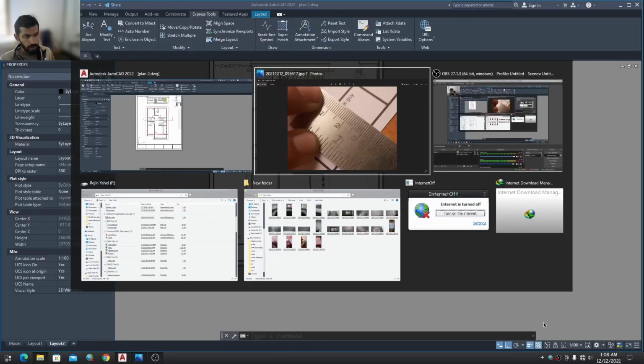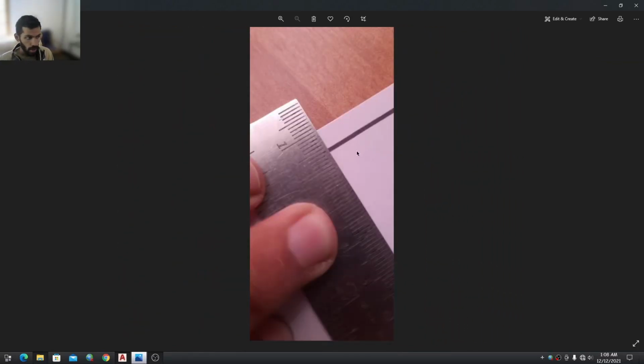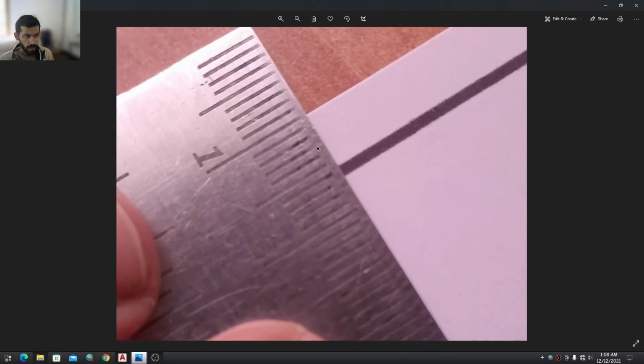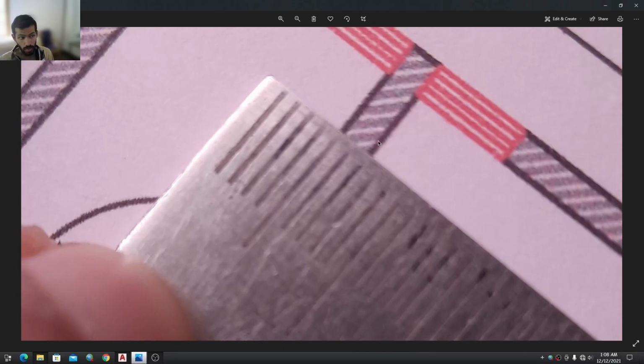So an important point to consider: I have to draw everything in millimeter, nothing more. If I try to take a printout, you can see that the whole size, this was 20 millimeter. The margin was 5 millimeter. If you count from here, this is 1 to 1.5, this is 5 millimeter. And the thickness of the wall was 200, but it is scaled down into millimeter, which is 2 millimeter. 1:200, it is not 200, it is 0.2. Okay, this is 2 millimeter. How can you get it?